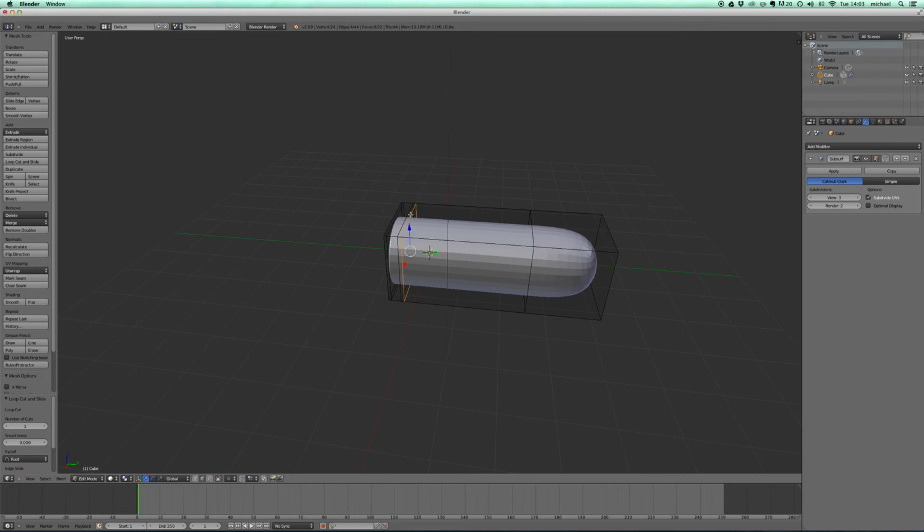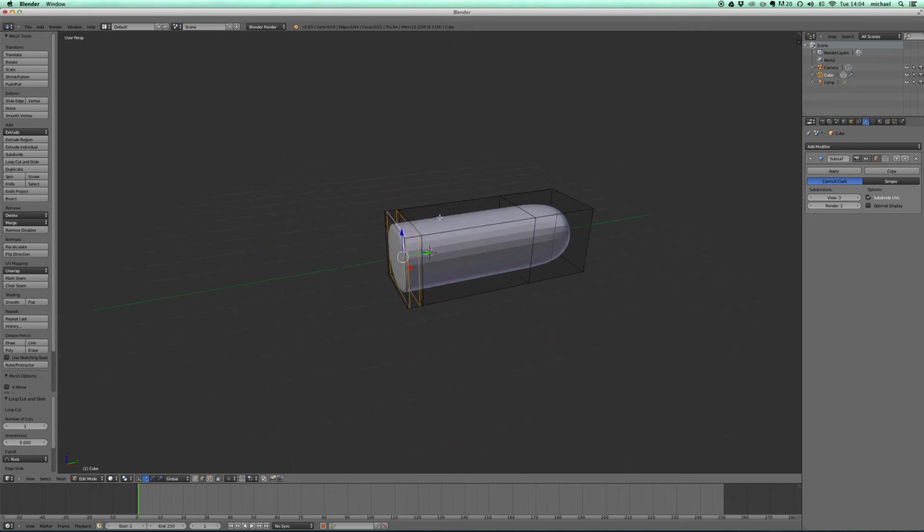There you go. This is a bit hard because it looks a bit laggy, and the reason is because I'm doing screen capturing and 3D animation at the same time. Never a good idea. So I'm pressing Alt, and then Alt Shift click, and then I'm going to grab, and then I'm just going to Shift select these last ones. So now I've got those, I can scale them up. So I go to the scale button here, press the little white circle in the middle, and then I can scale the whole lot up.